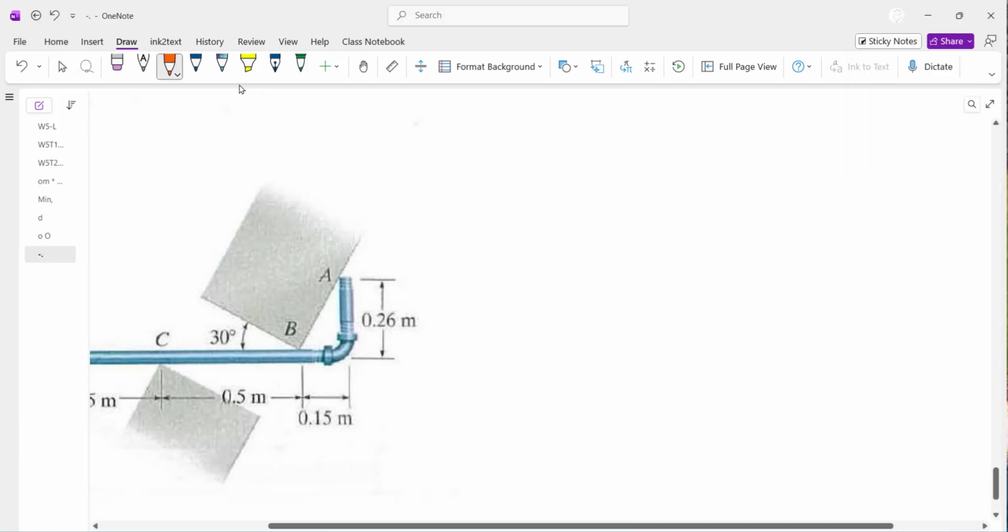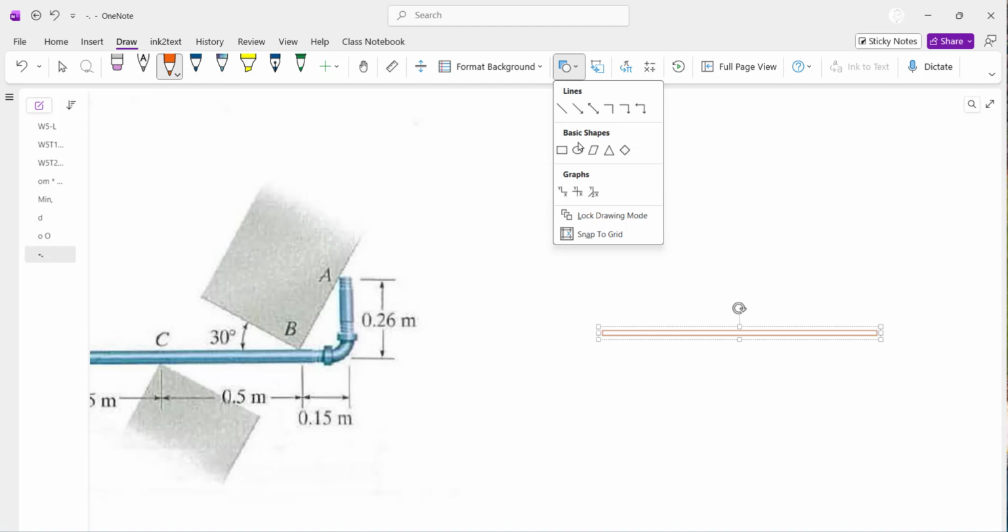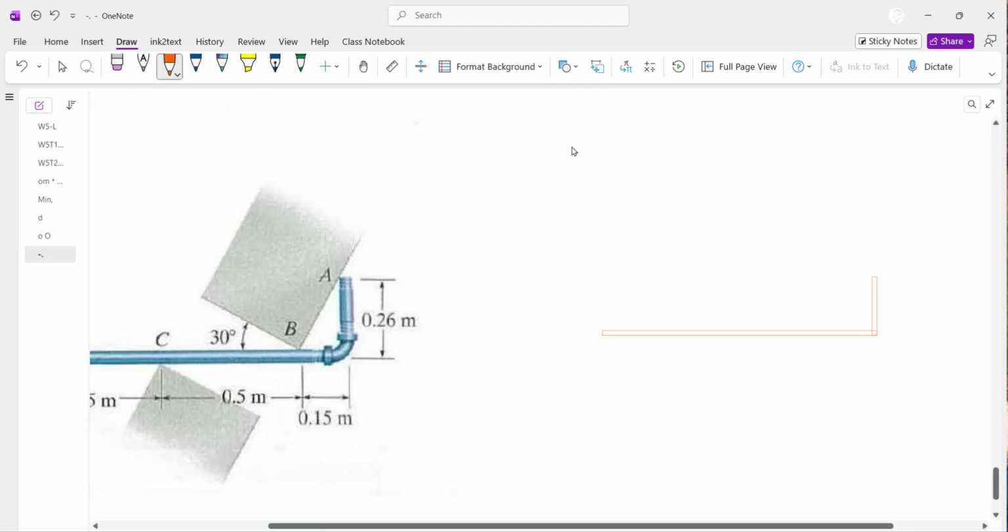So I'll just make the free body diagram, assuming that this is my pipe, right? So this is the bent pipe, and at A, sliding direction is here, normal to that path of sliding is normal to the concrete. So I would add a reaction force which is normal to the direction of sliding, not normal to the pipe.